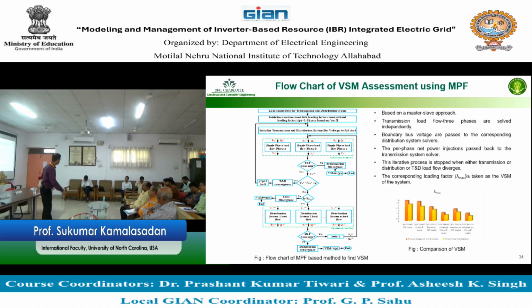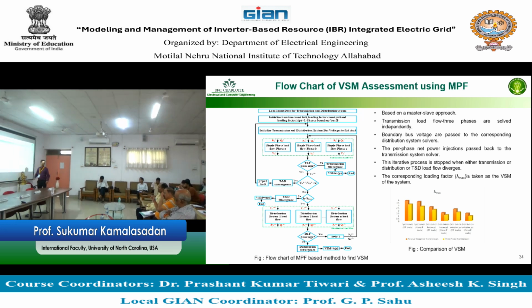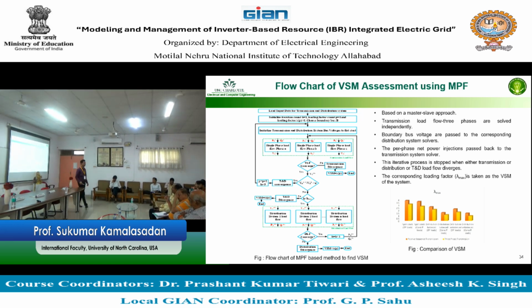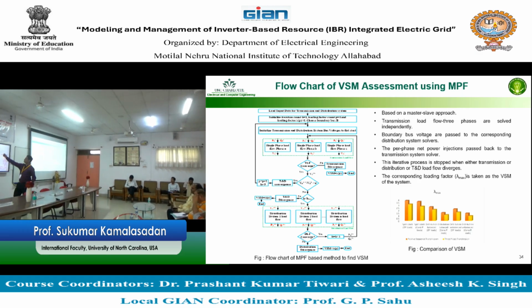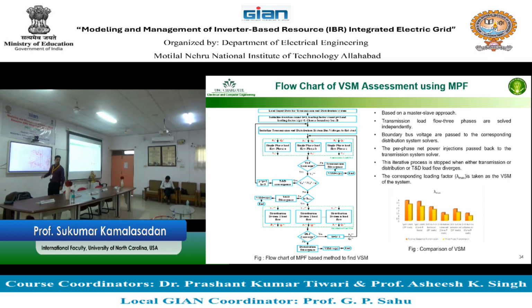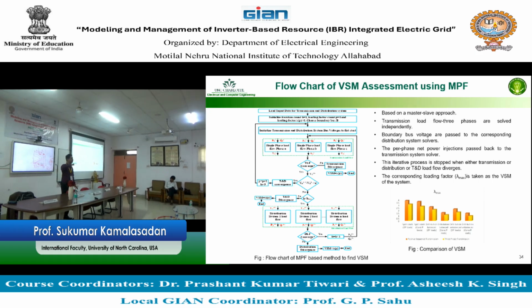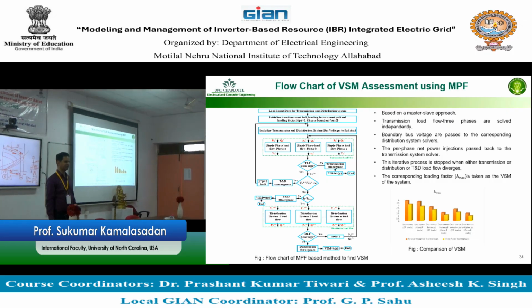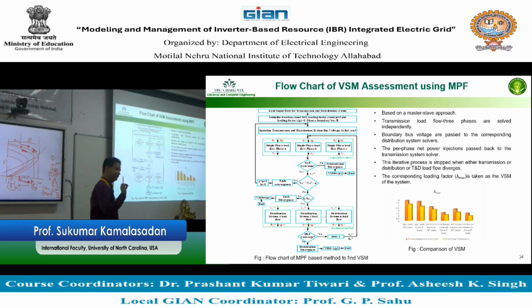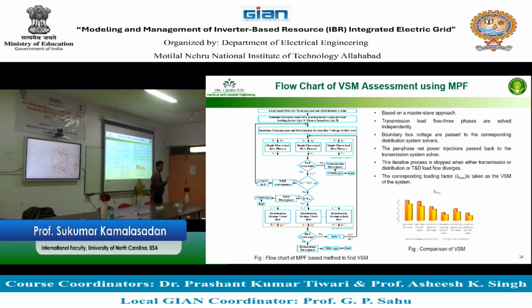Oh, another question. Can you make this PV curve robust? Can you load up to four without doing anything? If you can improve this voltage shape, go like this, then I think you have margin. How do you improve that voltage shape? Dynamic compensator. You should have some kind of voltage compensation. Voltage compensations are one way to take care of this.